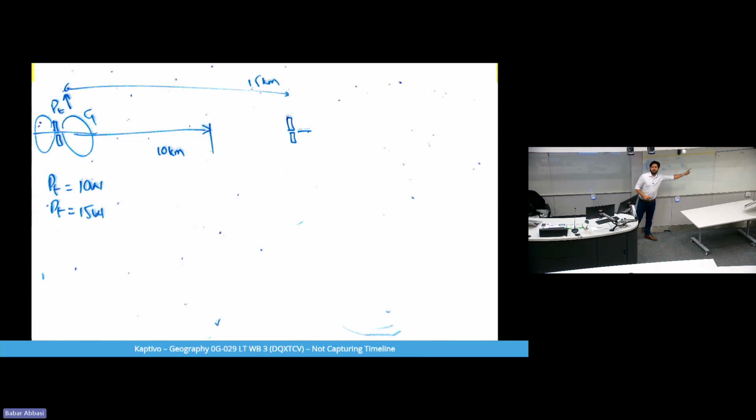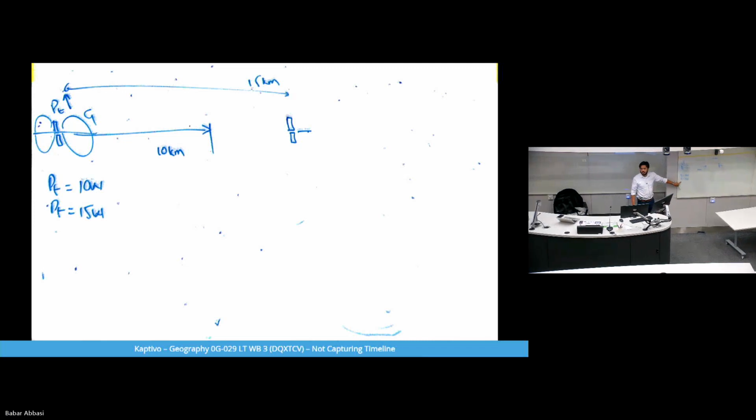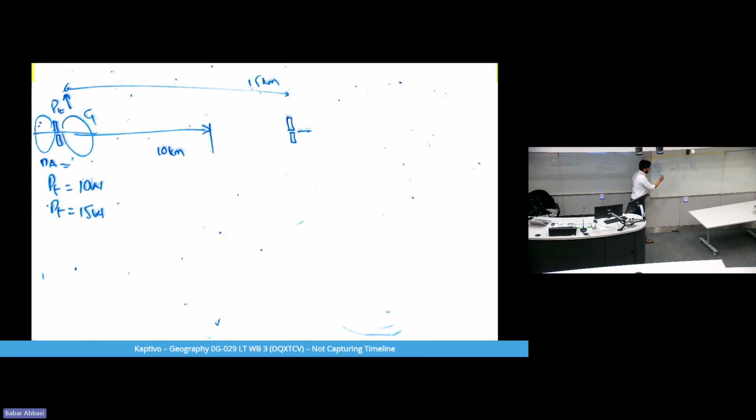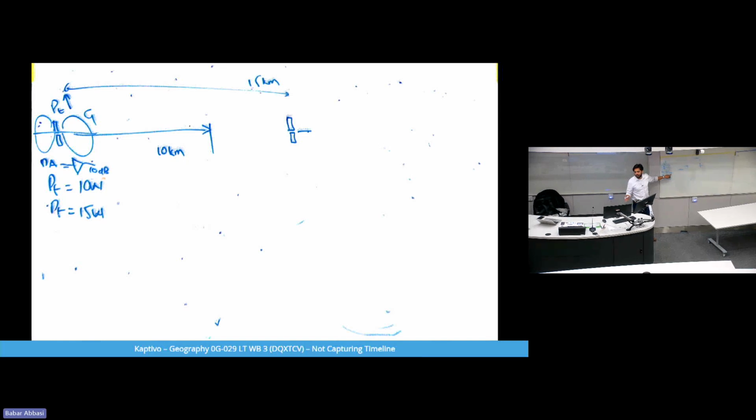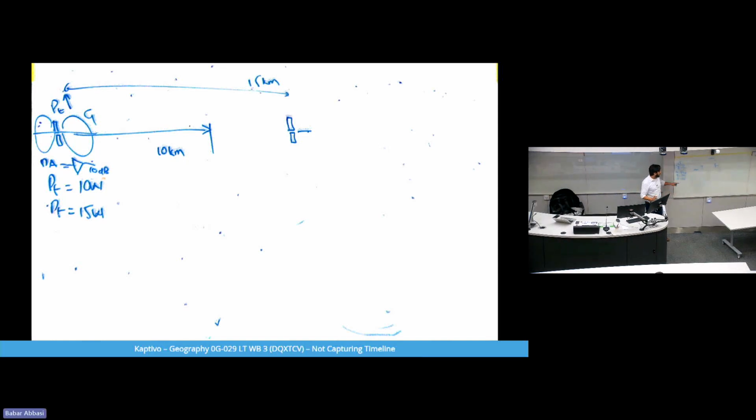My energy will be enough to get here. Now imagine my antenna cannot draw this much energy from my source, so it is already at its maximum power limit. Or the power amplifier that I have has a maximum gain of, say, 10 dB, and that's the maximum energy it can give me. So it's very power amplifier specific. If I have this scenario, what else can I do?